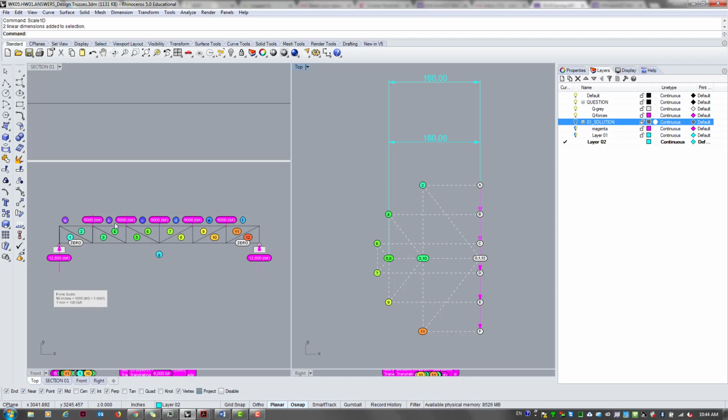So now something is not working because it doesn't completely match the geometry of the truss, right? The easiest guide to use is this diagonal line, and for example, the force in member 1, 2 should be parallel to this.